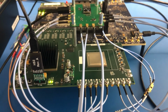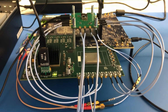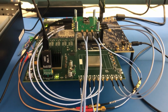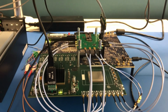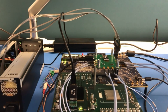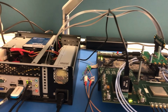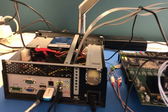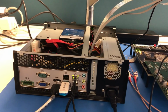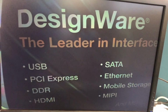implemented in an FPGA in this purple board, together with some additional housekeeping components. For example, it includes a DMA engine that collects the incoming pixel information recovered by the CSI2 controller. The board is connected to a PC via PCIe, where we're running the software drivers and application to configure the entire pipeline and make the necessary transformations to drive the HDMI display. And well, here it is. We're capturing a nice banner that we had sitting here, and we're projecting it on the display.